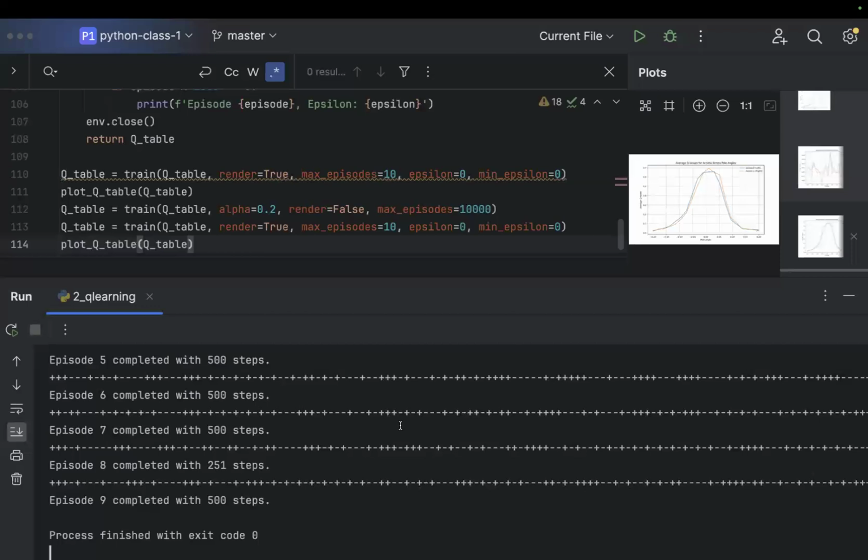So moving to compensate that particular one. Where it might help is where you have a combination of velocity, angular velocity, and angular position that are really required to use a kind of fine-tuned decision around that particular value. So in transition states, if the cart is a little bit inclined, but it's also traveling, and there's also an angular velocity that is pulling it up already.